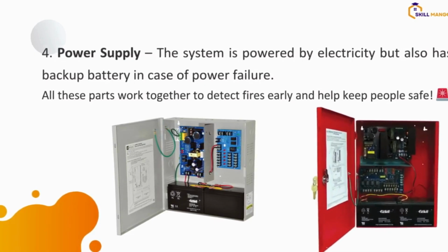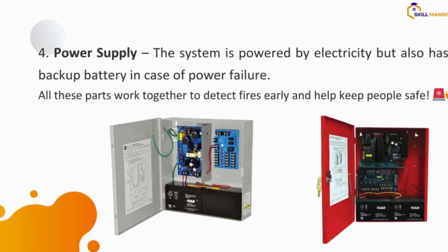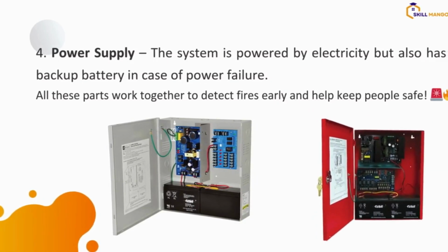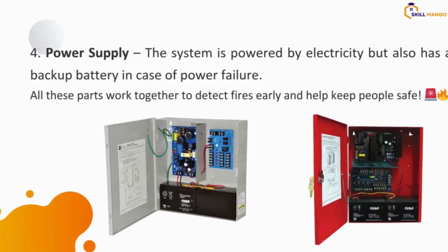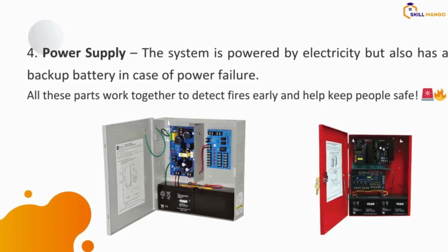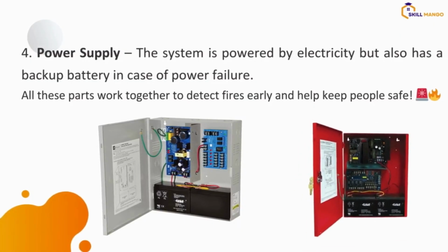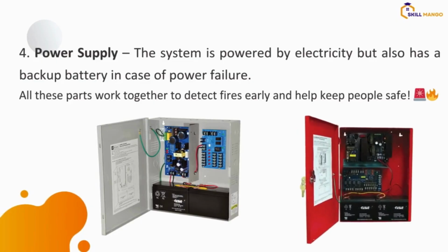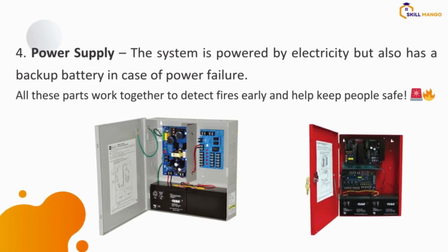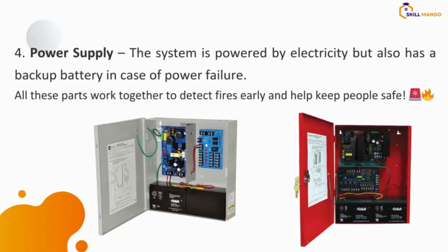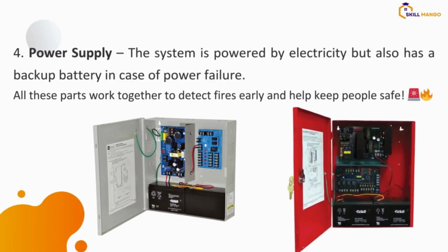You can see it mostly uses two batteries, which is 24 volts. So all the other devices on the network on the chain have to be 24 volts. It's very important to note this. And most of these panels nowadays have their inbuilt chamber for batteries. You just connect the battery terminals to them, and they power the panel itself. Instead of getting an external power supply, you just get a panel that has support for batteries.